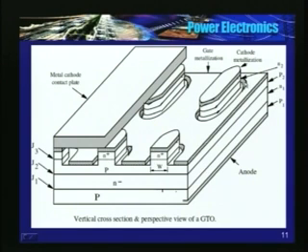See here again, a separate N2 layer, a small island of N2 layer. So this minus indicates the doping level is very low and the plus indicates doping level is very high. So it's similar to SCR. N2 layer is highly doped, N1 layer is very lightly doped.